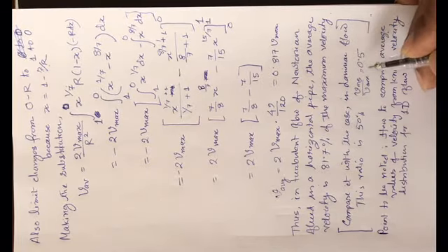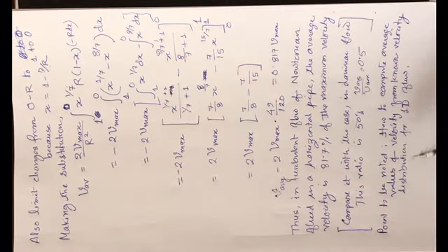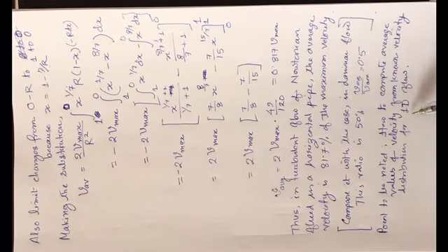By doing this simple exercise, what we have learned and can apply in future is how to compute the average values of the velocity from the known velocity distribution. Of course, we have done this for 1D flow, one dimensional flow. The flow is happening only in x direction.